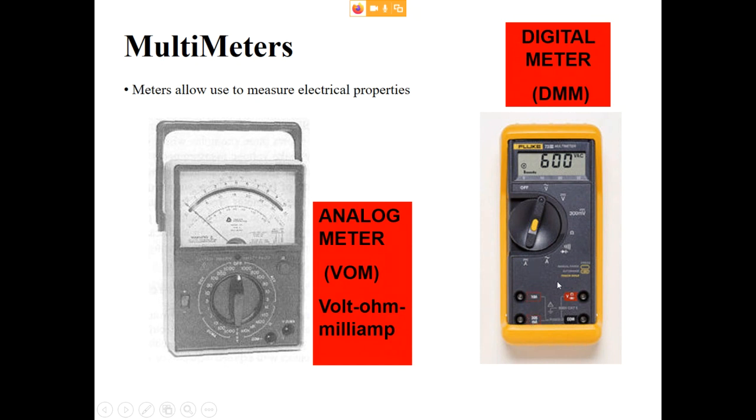And the reason for that is because voltmeters measure voltage in parallel, but current meters measure it in series, and so they have a very small resistance. If you plug into these terminals with the A on it, you can blow a fuse. Okay? If you blow a fuse, obviously it's going to cost you some money, because you have to replace that.